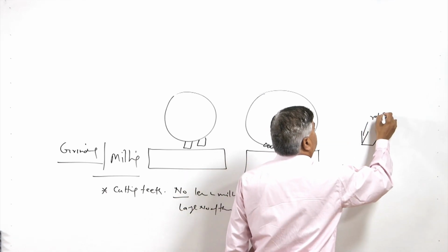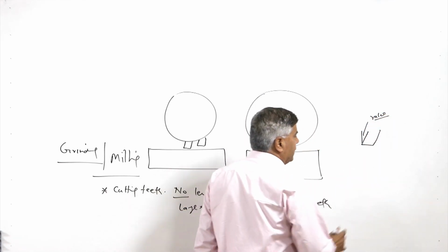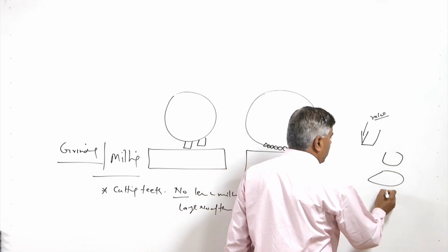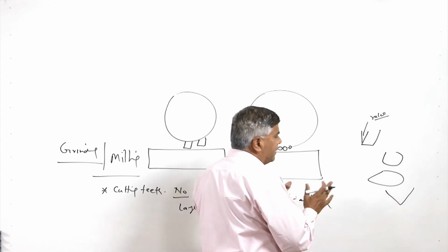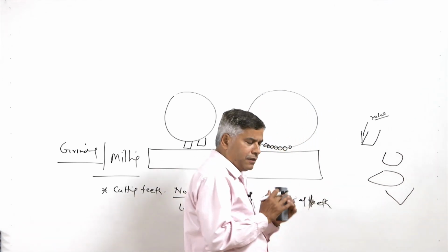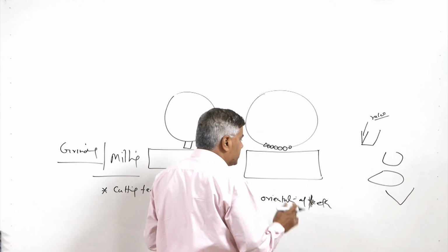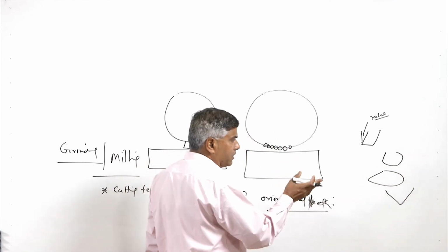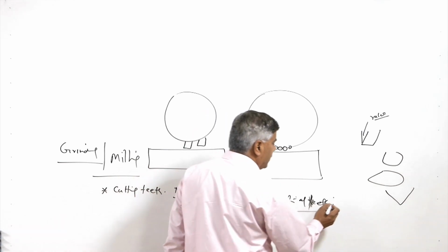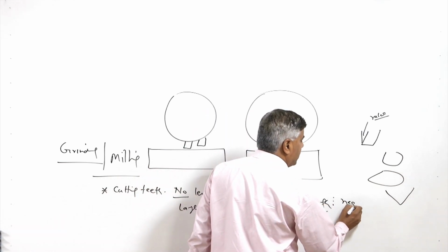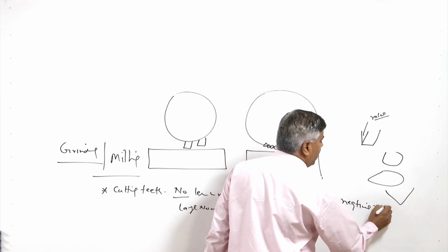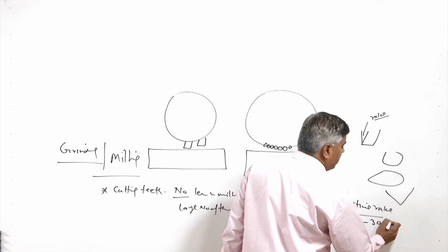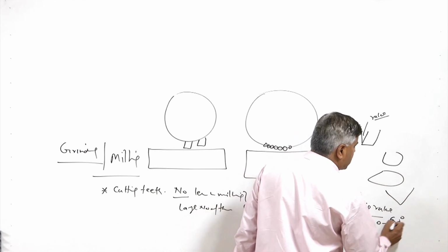So, this is how it is defined as the rake angle for the milling machine, while the grinding wheel uses abrasives. Abrasives have different sizes, shapes and orientations. So, mostly the orientation of the abrasives in grinding is such that it offers a negative rake angle during grinding, which generally ranges from -30 to -60 degrees.